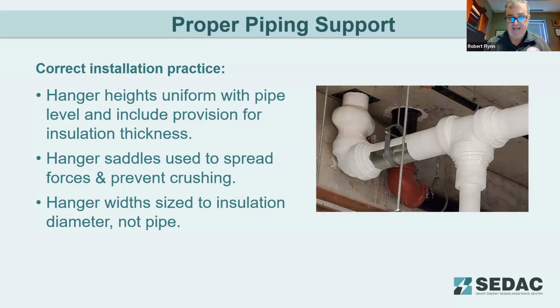For example, if they have an inch and a half of insulation running through the hangers, they might not drop the hanger enough, or they might drop it too much, and that's when you have that up and down, that non-uniformity of how the pipe was originally hung. So once again, the coordination between the mechanical, the plumbing, and the insulation installer is very, very important.